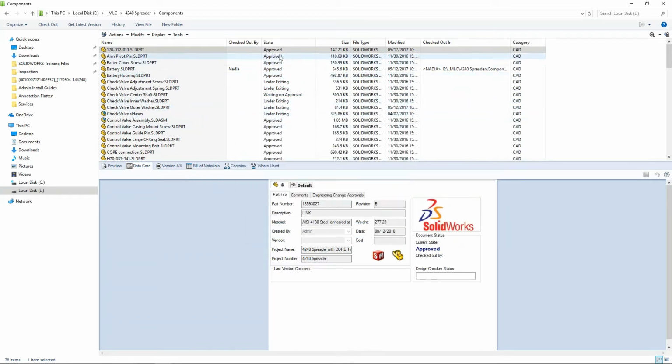Now, it's hit the approved state, but I want you to also notice that this file has also been bumped in Rev. So through those transitions that I showed you in the workflow, I do have the ability to automate certain tasks: write signatures, bump the revision, add data, take away a watermark. Lots of different functions are available in those transitions.